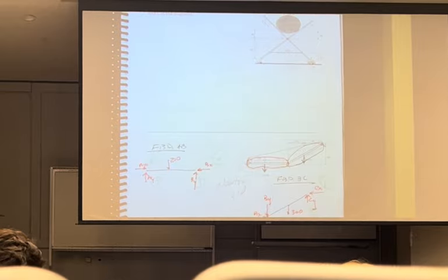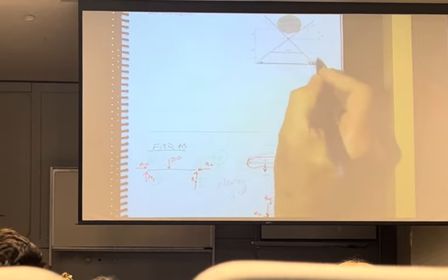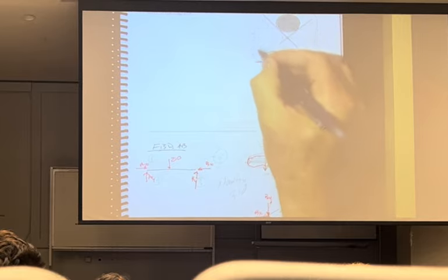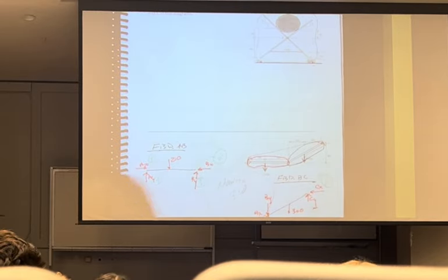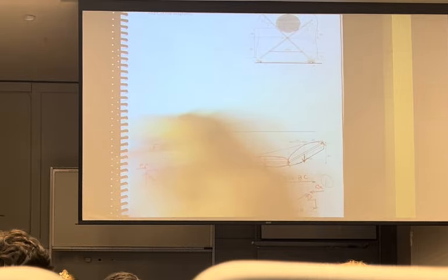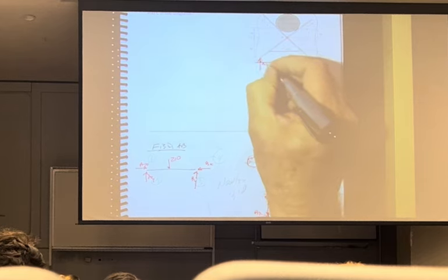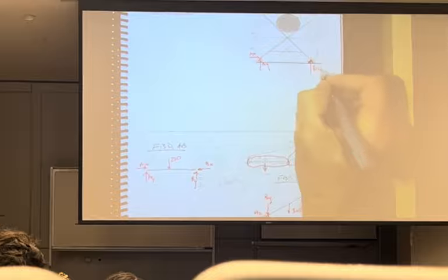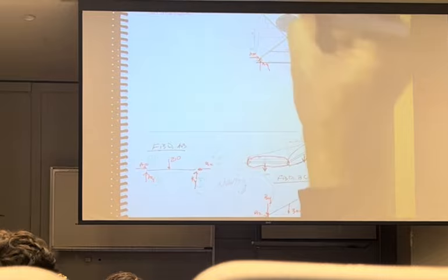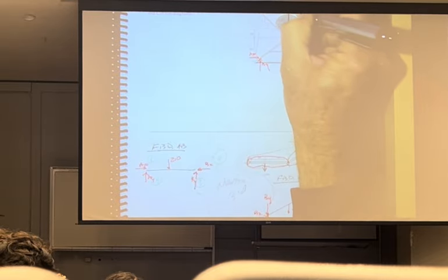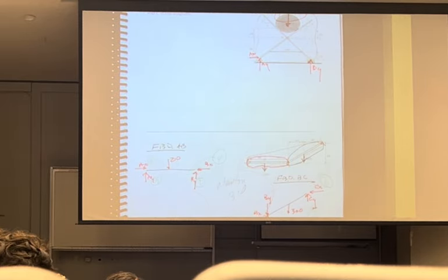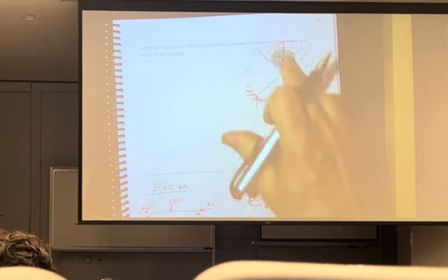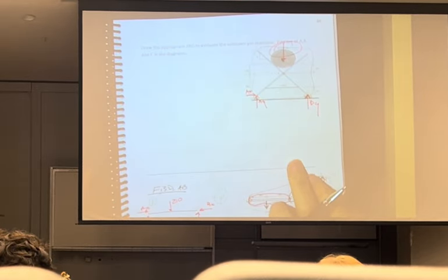So by doing a free body diagram that looks like this, I can accomplish my goal because, in essence, this is an AY, this is an AX, this is some DY, and I have a weight downward, which is the 260 pounds. So, can I solve for it? Yeah. There's 1, 2, 3 unknowns.